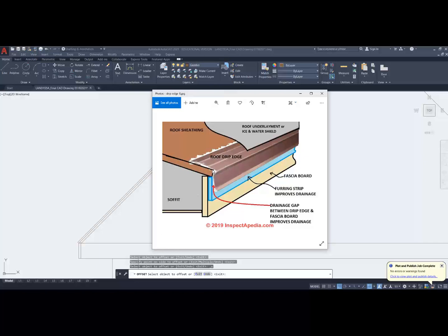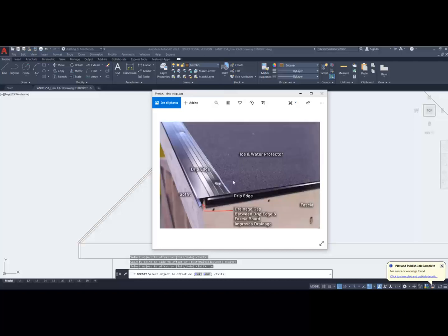then you put the ice and water shield on top of it. And this piece of metal has different sort of features to it. So you'll notice where you actually put in the nails back here, there's ridges. And those ridges prevent, even though it's on a slope, when you have high winds, the water wants to migrate upwards. And those ridges provide basically a seal between that and the ice and water shield and protects this corner where all this wood is.